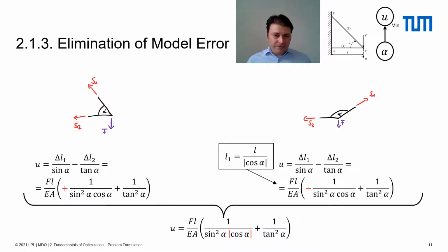When we looked at this expression, so at some point you need to express your displacement, the vertical displacement of your node Z, as something that depends on the extension of the two rods.